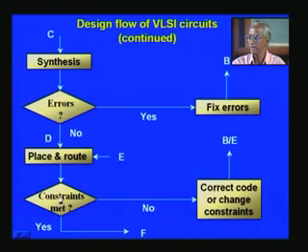And once again you will encounter different errors or limitations which will be reported if the constraints are not met, such as, let us say, the frequency of operation you have specified for a particular FPGA as 100 megahertz, but it has reported that it is able to give only 60 megahertz. So if you take 60 megahertz for your design, that's no problem.